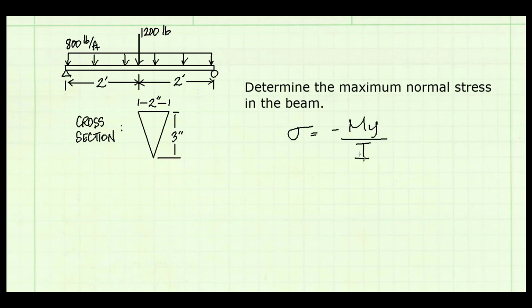I'm going to use the flexure formula to find the normal stress. To find the maximum stress, I need the maximum moment, and I also need the furthest distance from the neutral axis. So let's get the moment first by drawing the shear and moment diagrams.